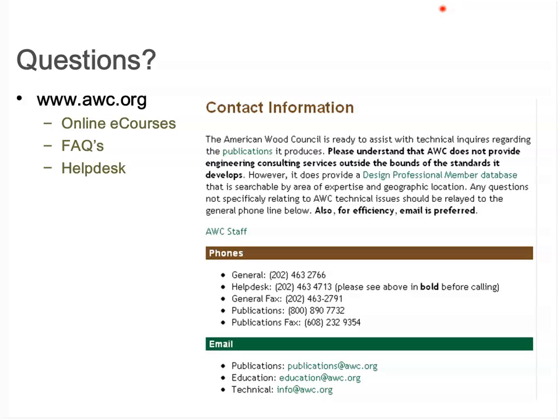So, next question: how is deflection calculation affected by roof holes due to skylights, duct penetrations, or roof access penetrations? I believe in the standard, and I'm gonna flip through it here real quickly, there are some limits on the openings that are permitted.